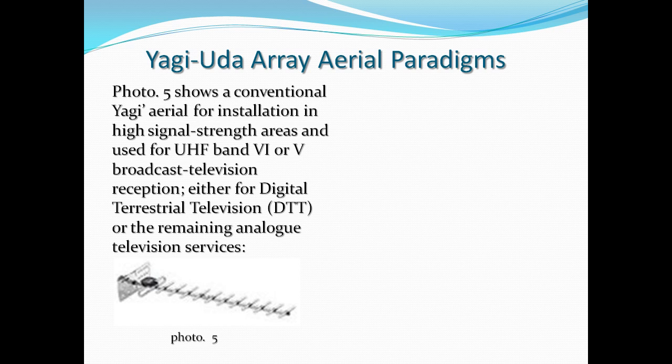It's true to say that virtually all high-power main television UHF transmitter stations in the UK radiate their transmissions in the horizontal plane, whilst virtually all relay transmitters in any given main station transmitter group radiate their transmissions vertically polarised.